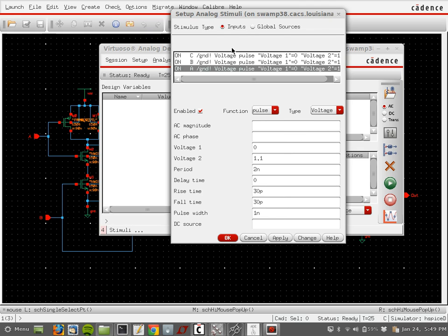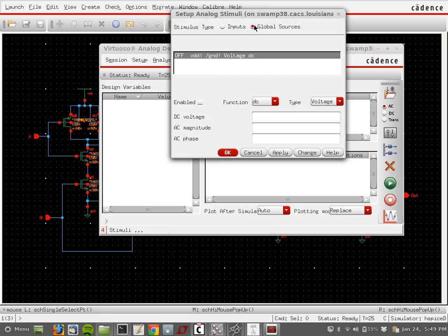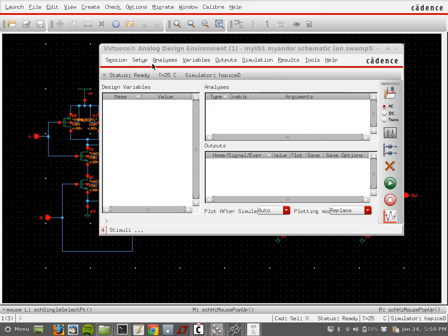Okay, so we're done with the inputs. But remember, we have VDD. We still have to set VDD. We haven't set it yet. That's when we go to the global sources. So we have inputs and global sources. We move on to the global sources. We have VDD ground, we enable it, and it's DC, right? It's not a pulse. So we leave it as DC and we put 1.1. Apply, okay.